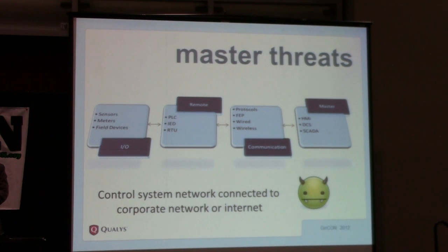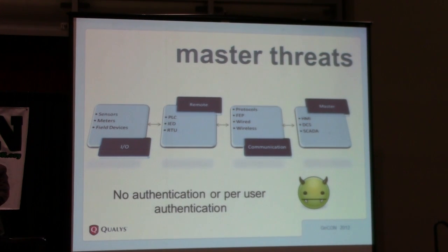And all of you in this room know that there are many different secure ways to do that, but the way they implemented it was to just connect their control system network to the internet, to the web server, which always spews out, okay, there are outages here, here, here, and whatnot. As I said, there are a lot of other secure ways of doing that, but the way they decided to do it was to connect the control system network directly to the internet. So that's the number one threat.